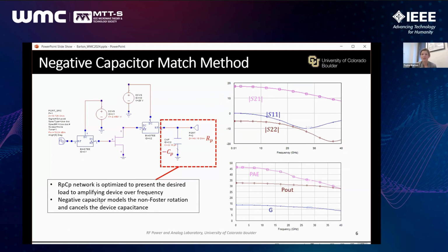But as was mentioned in previous talks, sometimes we don't want to load pull the device because it requires intensive large signal simulation or measurement, and it's resource intensive to do so. So rather than performing a more traditional load pull, we can also use this simplified model for the device.